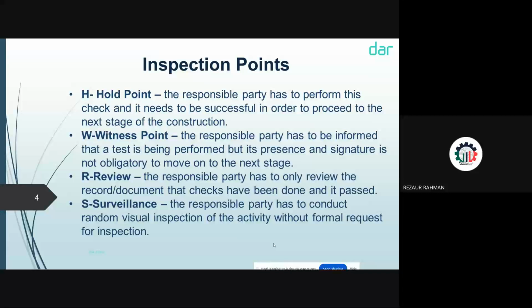For a factory? No, but for the sewer line, the overseeing consultant from Taka is doing this witness for the test. Now, they are witnessing, but the test is done by the third party. At site testing, the third party is not involved. You can consider that as an inspection. Testing means which is third-party relevant, that means compressive strength, FDT.